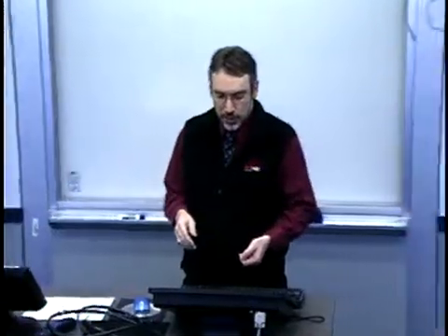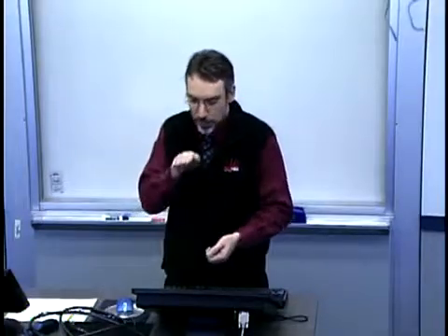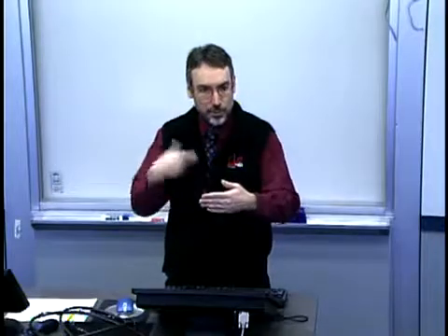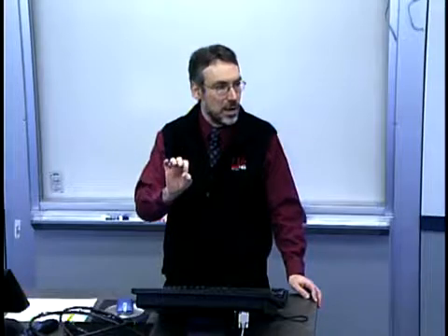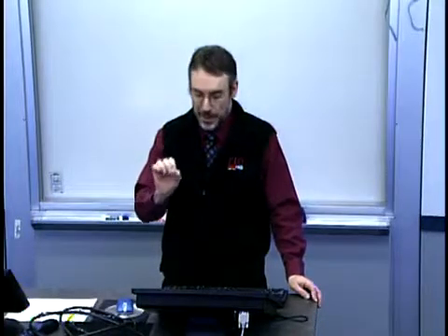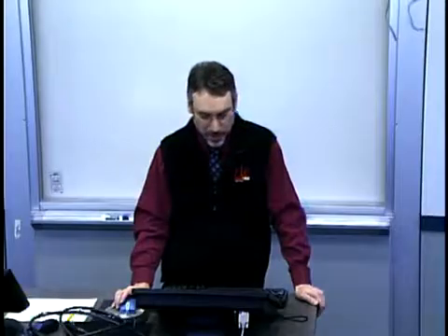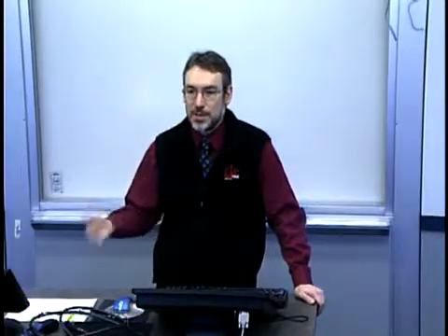So here's a basic turning process. We've got a work piece. Under computer numerical control, CNC, we've got the ability to cut into that workpiece, which is rotating, to try to get to workpieces of a specified diameter. So here's the diameter measured at a particular location on that workpiece as a function of 47, I think it's 47 or 48 different repetitions.